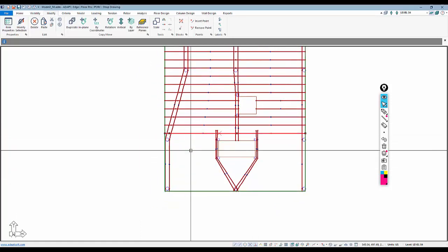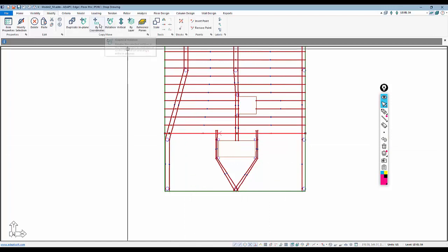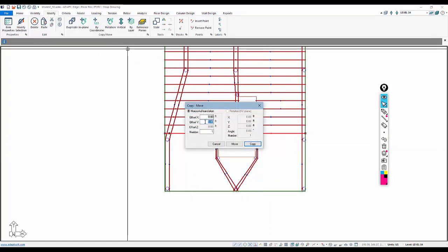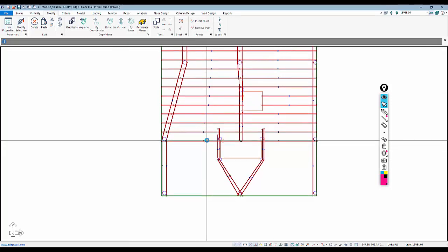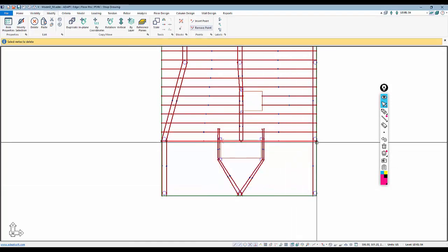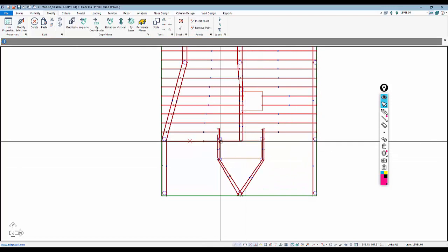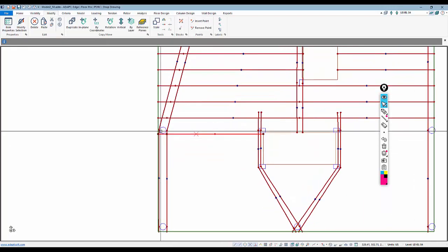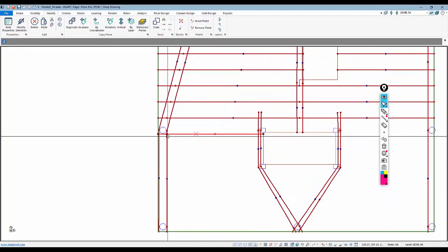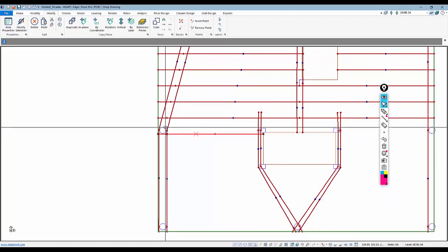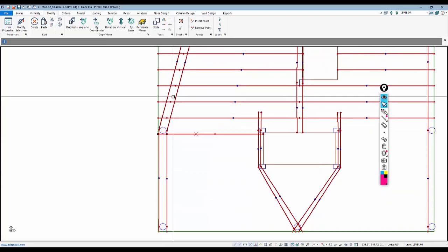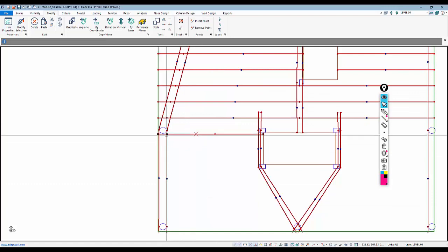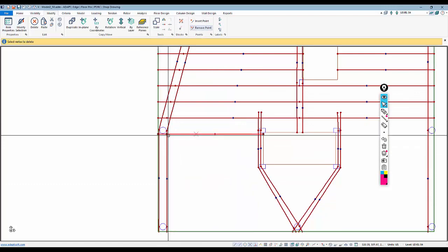Okay, we're now going to take this tendon, and I'll copy that down, use my replicate again. We'll do this -4, just one copy, and again we'll use the delete option to manipulate this. And I'll take this one down and copy. Now we really don't have a cantilever that's stopped in this bottom span. It starts to grow as you move vertically. So I'm also going to just delete out this extra point.